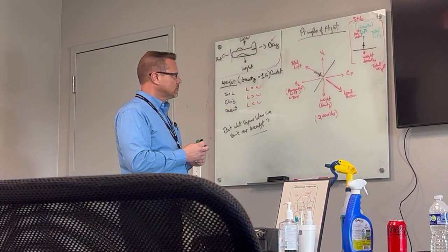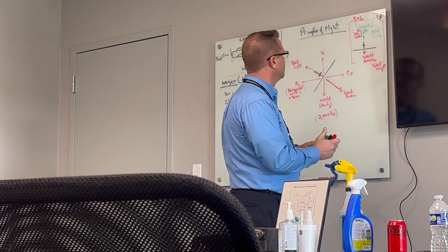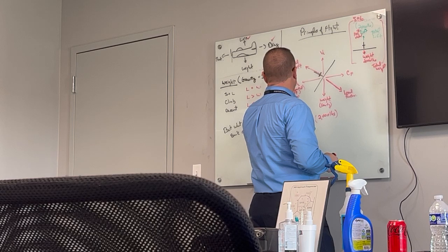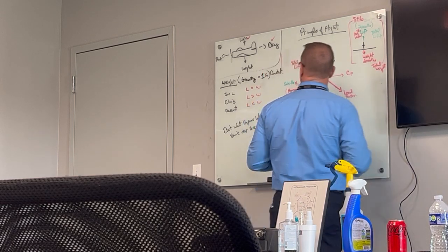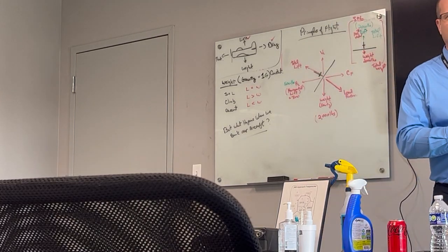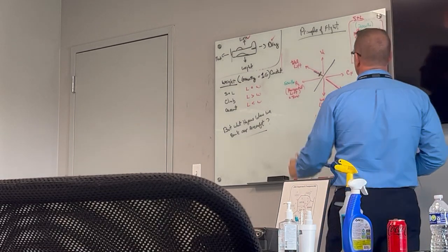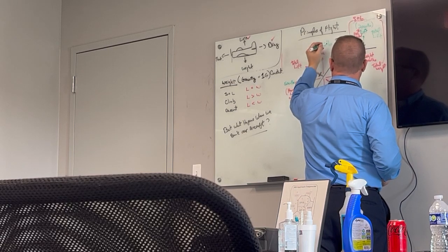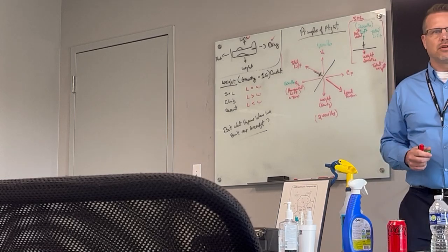So let's just say, for example, we had 2,000 pounds of lift up there, but we had to give 500 pounds of that lift from our vertical component to our horizontal component to pull us through this turn. Okay. So right now, if we did that and we didn't change anything else, we're only left with 1,500 pounds of vertical lift.